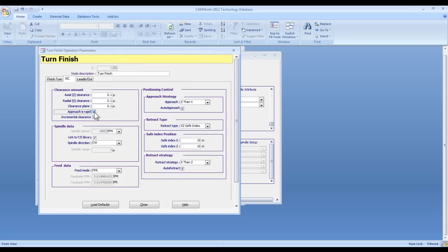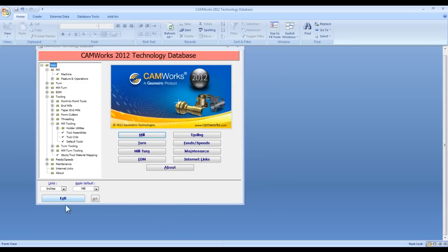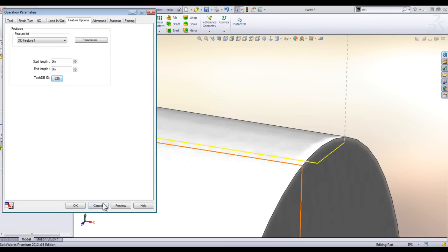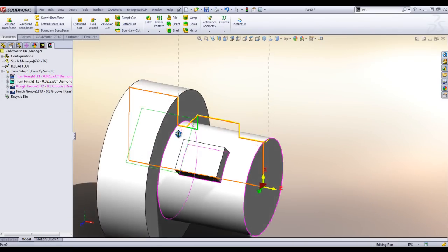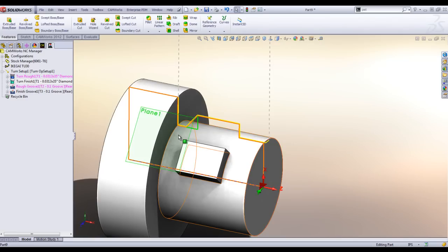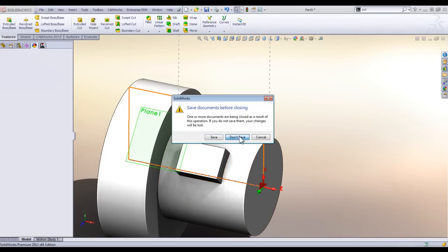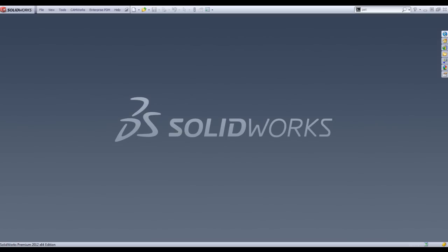The last thing I want to show before I finish up here is that they have developed on adding custom turning inserts to your parts, and now you can do it for a couple more things. You can do it for your roughing operations too. So I just wanted to go in here and create a turning insert and show you how you can make your custom turning inserts and use those in CAMWorks.